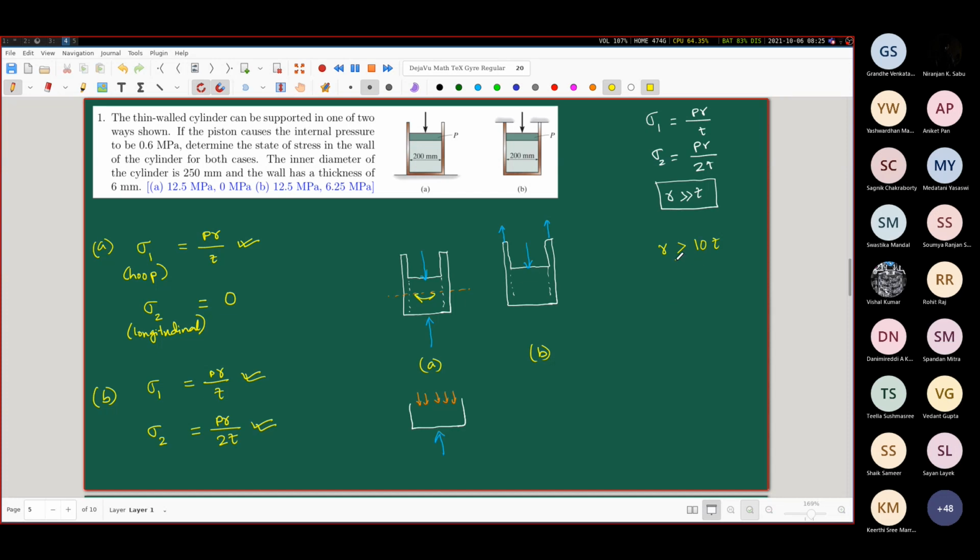As I told you, some real values should always be at the back of your mind. When you are talking about Young's modulus, don't just arbitrarily say 10,000 GPa, because there has to be a material in the actual world which has such a high Young's modulus. Steel has a Young's modulus of 200 GPa. Don't forget that. Aluminium is in the range of 70 GPa. Also remember values like atmospheric pressure and the density of water.